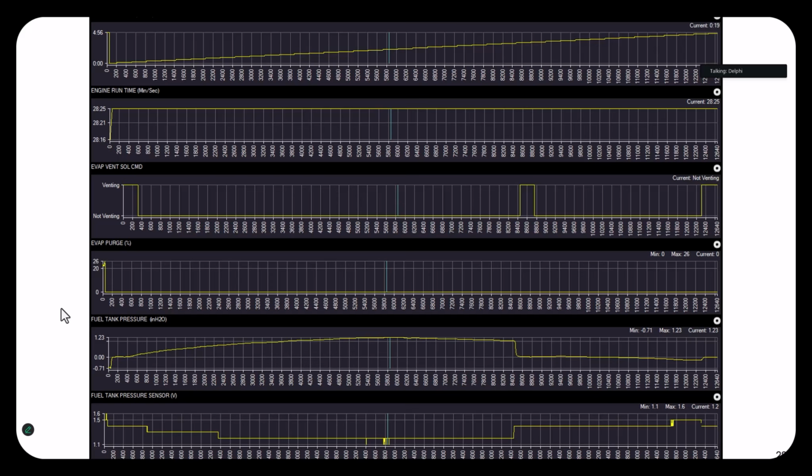You'll see the scan tool say no data. Basically, your computer's gone to sleep. When it begins this test, say at 5 minutes on this car, you will see the scan tool come alive. That's how I got this data. So that data is broadcast to the scan tool so I can see these test results.